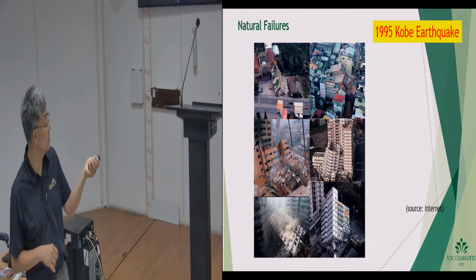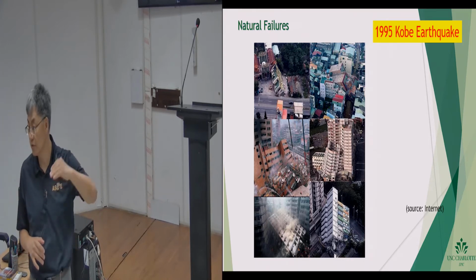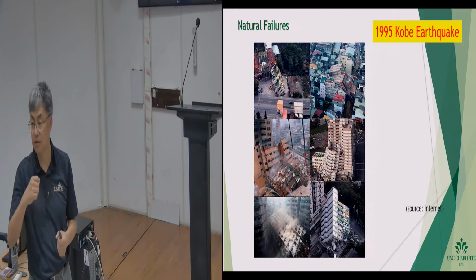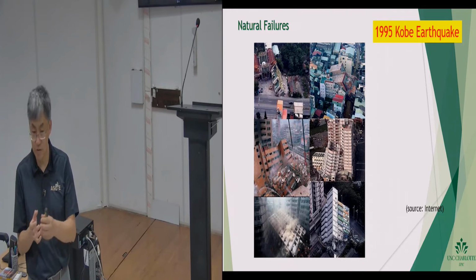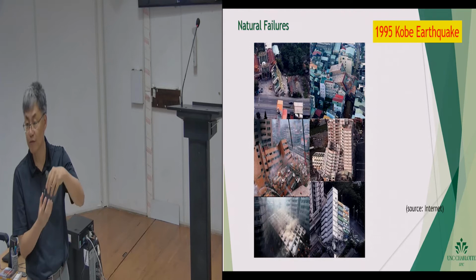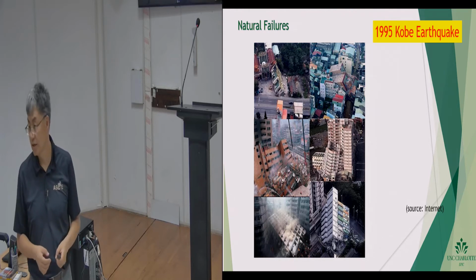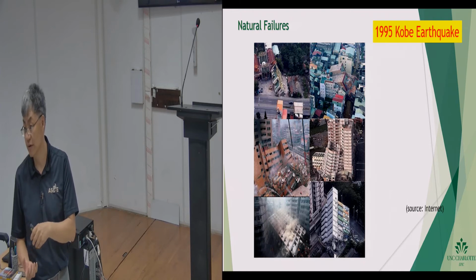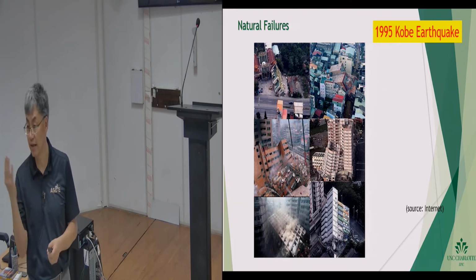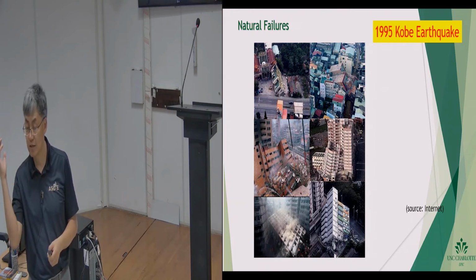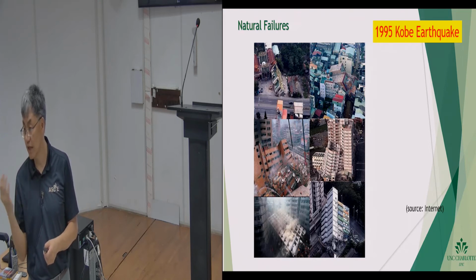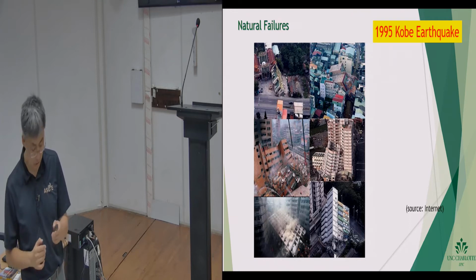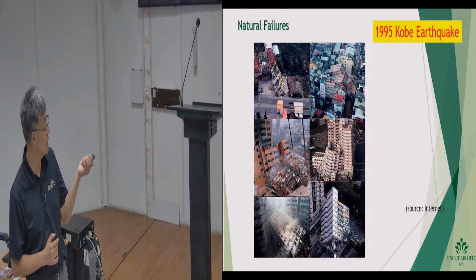This kind of incident becomes a very long battle for the engineers. You have to prove a lot of things. You do a lot of drilling. You get the soils out, and then you have to do a lot of triaxial tests to show that the soil has either liquefied or not liquefied. You also have to do a lot of dynamic analysis to prove that the shaking force was strong enough to cause the building to collapse. So a lot of those investigations have to be done.